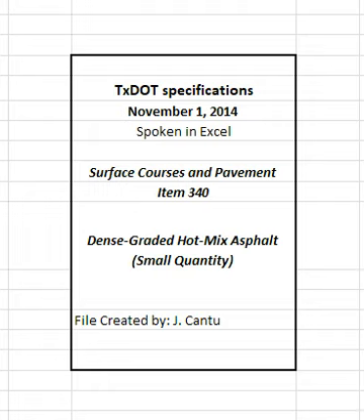Dry the core holes and tack the sides and bottom immediately after obtaining the cores. Fill the hole with the same type of mixture and properly compact the mixture. Repair core holes with other methods when approved.